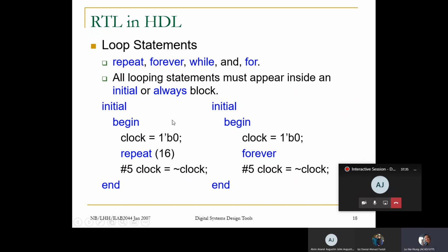Because any synthesis tools, when they look at initial, they will ignore the whole thing, or they return you with some junk that cannot be translated into hardware. Now, more modern tools may give you a warning saying that you're using an initial statement in your design. But if you do not have any syntax error, it will pass, and this can create a huge problem in hardware design. So avoid using initial statement in your hardware design.